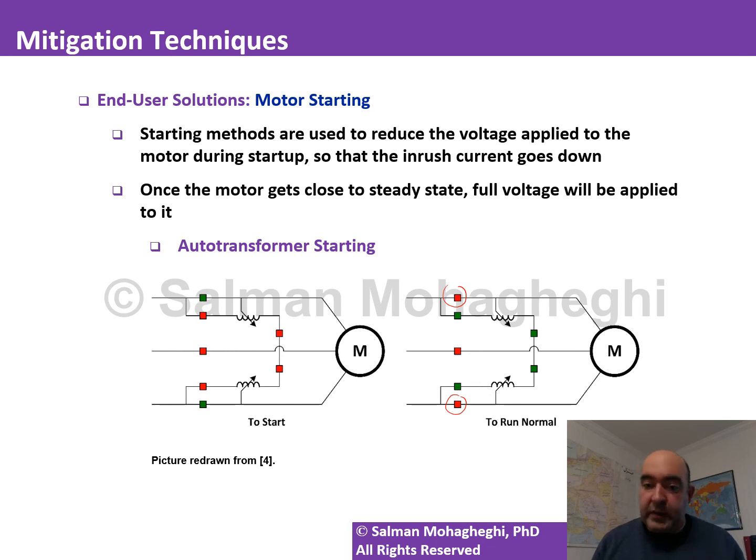And as you know, imbalance could lead to, I'm sorry, the sequence components, not harmonics, sequence components in the system, which would lead to additional overheating and things like that, which is not desired. So for large motors, if overheating is a significant problem, you may want to make sure that you use a 3-phase auto transformer, unlike this configuration.